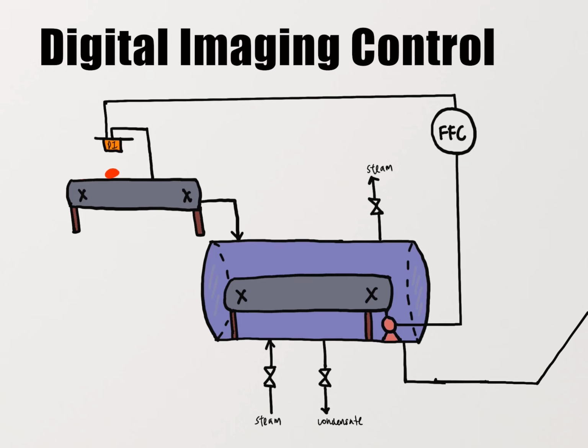If the DI sensor produces the red color band, the FFB is overripe. A signal is sent to the controller to increase the conveyor belt speed so that the residence time is shorter. If the blue color band is obtained, the controller will reduce the conveyor belt speed for longer sterilization. If the green color band is obtained, normal processing time is maintained by the conveyor belt motion.